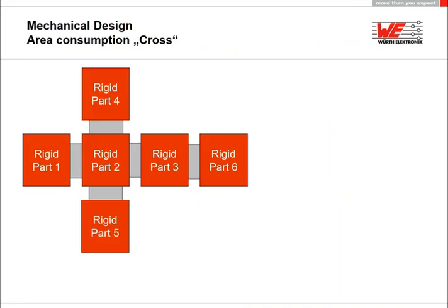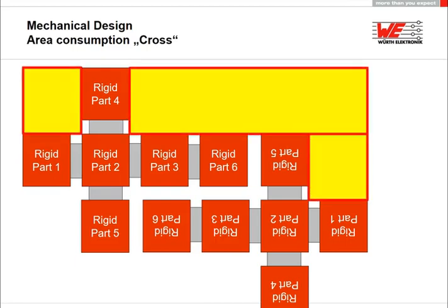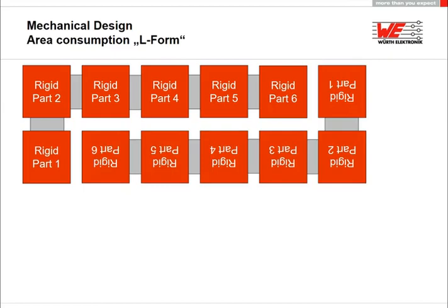Now, looking forward to the production, we have to state that this design is not the best we can imagine, as finally with nesting there is still a lot of area which could not be used for production. So a slightly better design is the so-called L form. That's even better to nest, especially for these two PCBs nested.